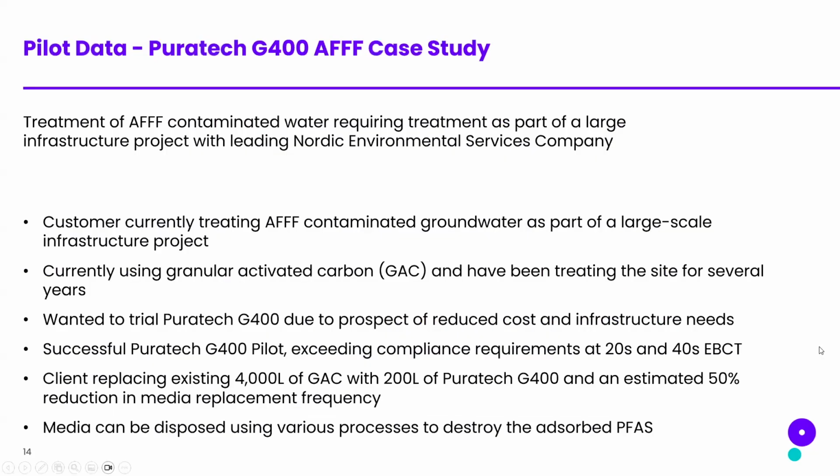So let's get into the first case study, which actually led to a full-scale application, and this was a site in Sweden that currently is treating AFFF contaminated groundwater. They were using activated carbon that they've been using for years. They trialed our material, the PureTech G400, running at 20 and 40 seconds contact time. So basically 2 beds in series, 20 for the lead, 40 for the total. They're replacing 4,000 liters of activated carbon with 200 liters of G400, and the G400s are operating at an estimated 50% longer time compared to the activated carbon.